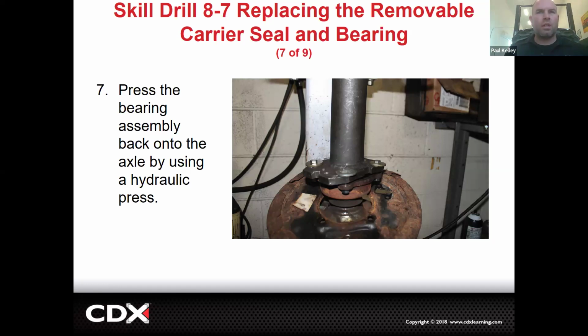If you're the DIY home mechanic, you know what you're going to do? You're going to buy an axle from a junkyard with the bearing already pressed on it. You know, put that whole thing in there. And it doesn't matter the gear ratio. It just has to be the same type of differential housing.